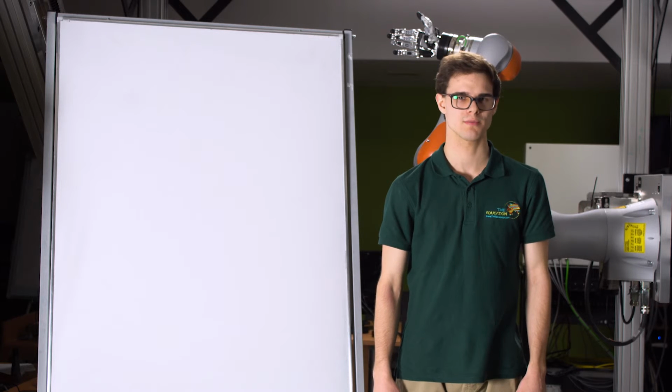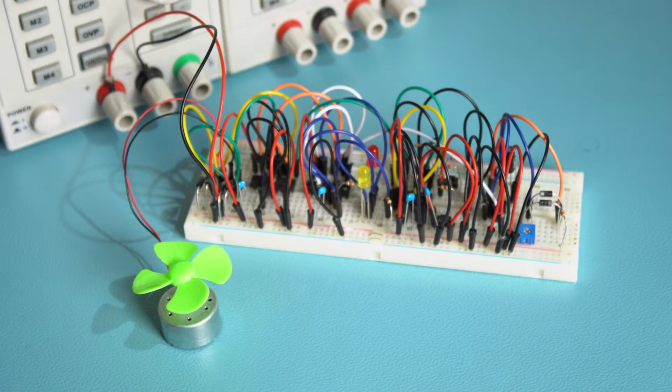You do not require symmetrical voltage supply. This is a diagram of the H-bridge with the motor switched on between its terminals. Note that in the previous solution we cannot allow simultaneous turning on of elements S1 and S3 or S2 and S4, or worse, all. How does controlling such a bridge look like? The keys S1 and S2 connect the output terminals to the supply voltage. The S3 and S4 keys connect the ground leads.